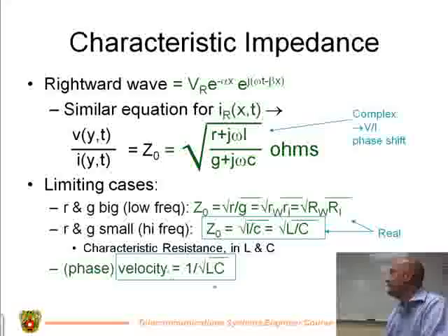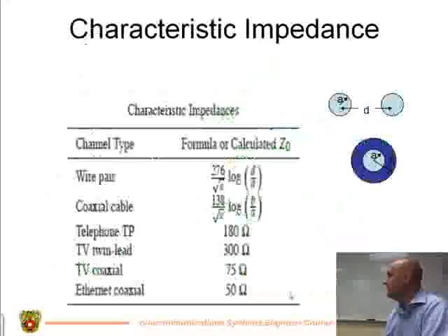The relevance here is we just need to know the phase velocity. This is the limiting case, and the reason I put this here is because it's only this when the frequency is high. But we're going to assume that the frequency we're dealing with is always high. In general, Z naught is the square root of L over C, and phase velocity is 1 over the square root of LC. And again, that doesn't model dispersion or anything. We're going to kind of ignore that.